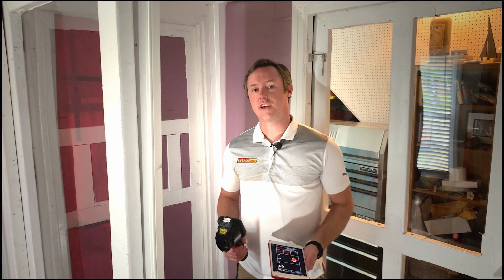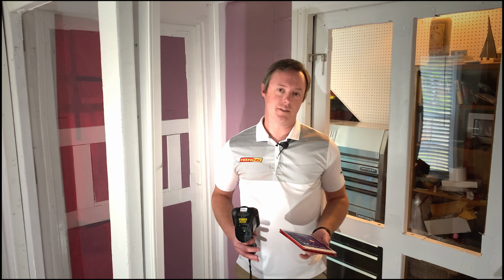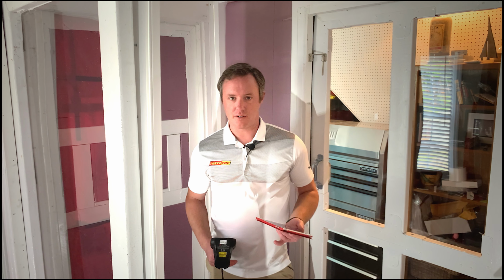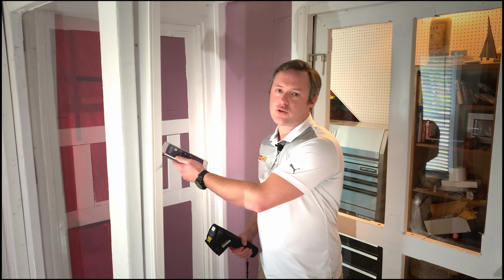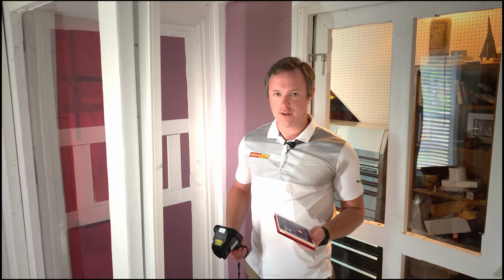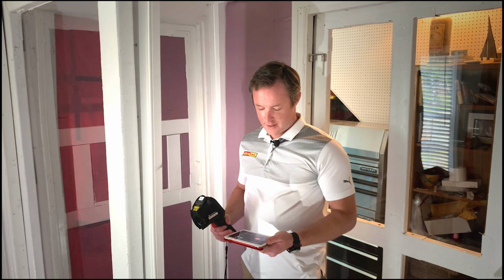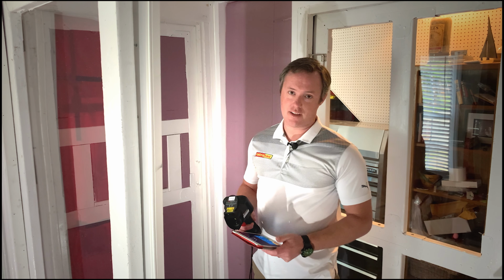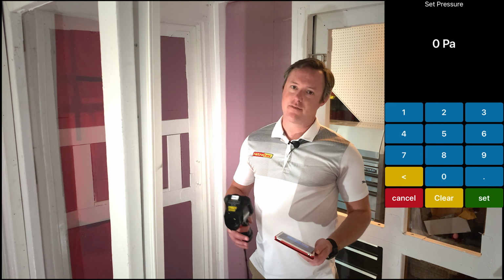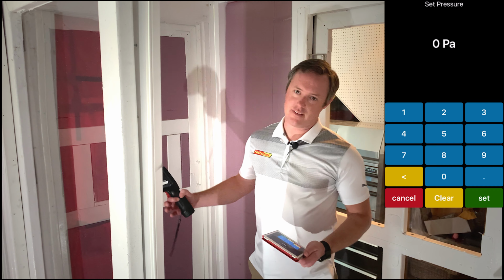So now I'm inside the chamber, and we're going to do the same thing that we did outside, but now looking at those leaks from the inside. So the color patterns that we're going to see are going to be the opposite, as I explained before. Now that we're in the warm interior space, we're going to see that cooler outdoor air move inward. So we'll set our blower door to 5 pascals, and then we'll do that same pattern. We'll go 5, 10, 25, and then 50.